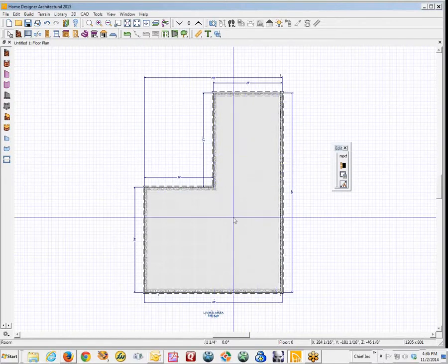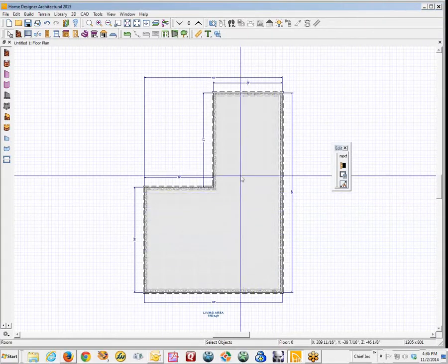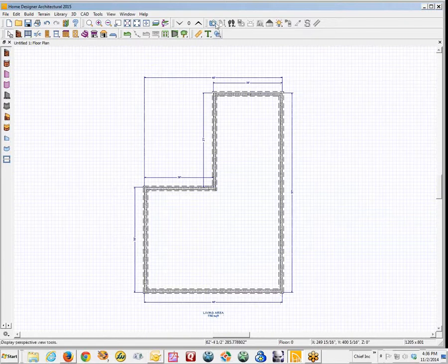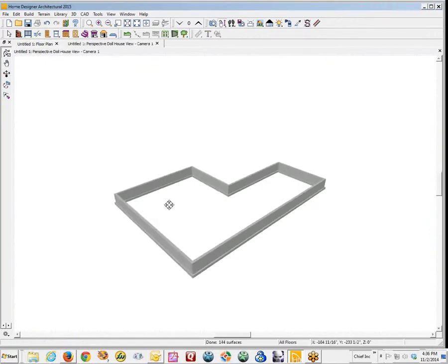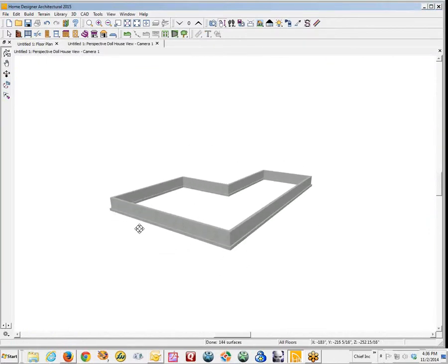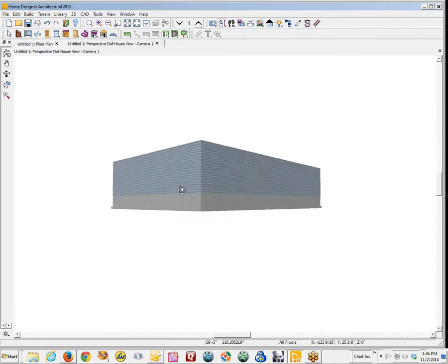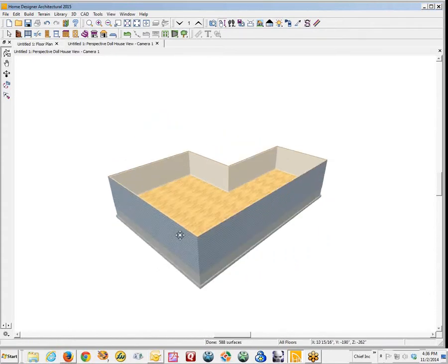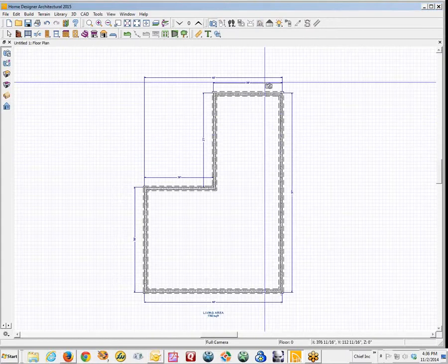And it's enclosed, so you get a dialog box. I can further program it if I need to, because it has a closed space in this software is programmable by its room specification dialog in terms of its three-dimensional height and so forth. Let me show what this looks like in a Dollhouse Camera. So that's what it did, because that's what the defaults told it to do. We'll go up a floor. There's the first floor without the roof. And it's just a mechanical device that follows settings. So most of your learning curve is going to be figuring out and learning where the settings are and what they do and why they do what they do.